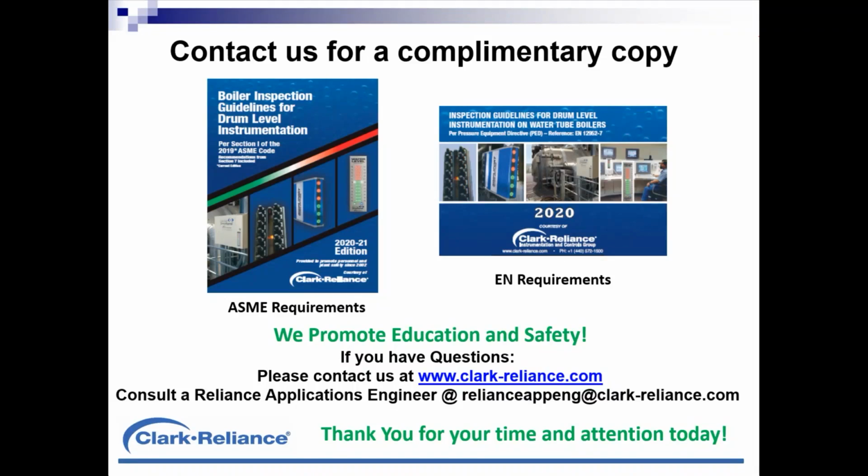Good. Thank you, Jim. There's one from Sean Bowler in Trinidad, and he asks about the frequency of doing calibration or function testing of drum level transmitters. Depending upon the type of device, if it's a conductivity probe device, there's nothing to calibrate because those sensors are on fixed locations.